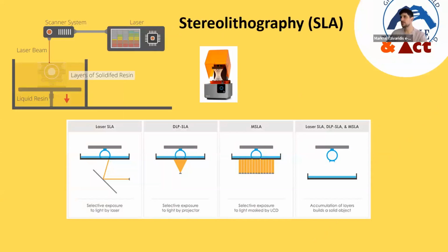The second one is the stereolithography process. Now, this process is a form of 3D printing technology used for creating models, prototypes, patterns, and production parts. It's a layer by layer way to create things, and it uses photochemical processes in which light causes chemical monomers to link together to form polymers. These polymers then make the body of a three-dimensional object.